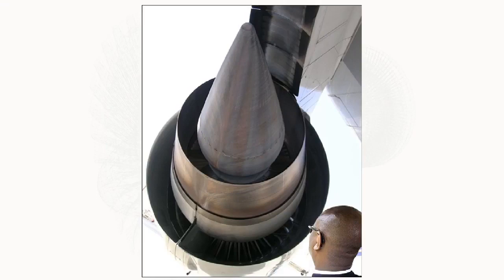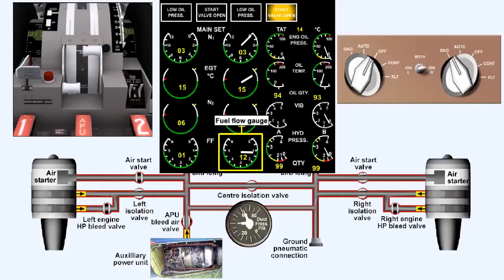Alternatively, if your starter crew trust you, and if it's safe for them to do so, you could direct them to the rear of the engine and, having selected relight, ask them to listen for the asynchronous ticking noise which two high-energy igniters make when they're feeding spark to two serviceable igniter plugs. Another cause of a gas turbine engine failing to start could be a lack of fuel, but this is fairly unlikely to occur on an engine that was working perfectly when it was shut down. A check of the fuel flow meter when the start lever is operated will give you ample evidence of whether fuel is being fed to the engine or not.